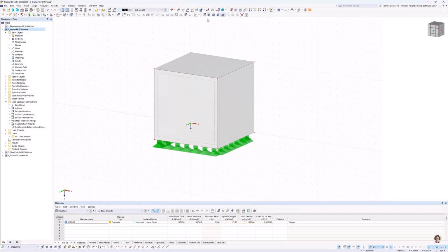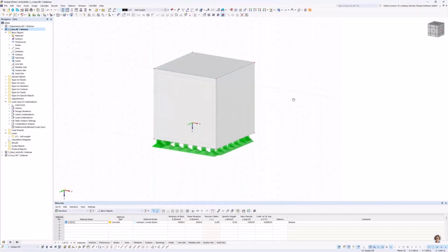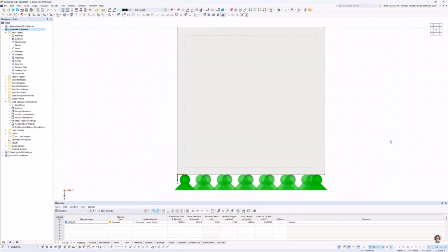And with that button here above, we set a new grid and a new origin. I click on that edge. So, now the front is our work plane. I change to the -Y view. And we start with the rectangular opening left above. So I enter the opening.